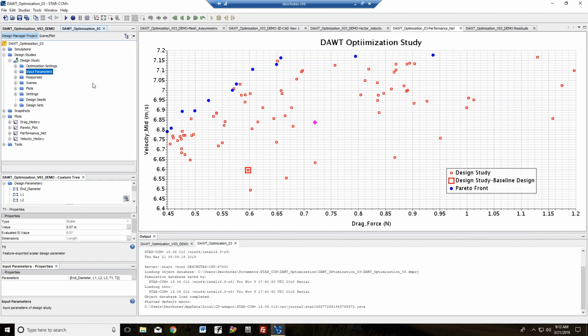And on the input parameters, you set this is the baseline parameter, this is a range I want you to look at, because that original sketch was a lot of geometric constraints. There are points that would come up with a nonsensible geometry. When you hit one of those points, it just throws it out, skips over it, and goes on to the next one. It doesn't hang up the software. So it really reviews the space automatically for you.